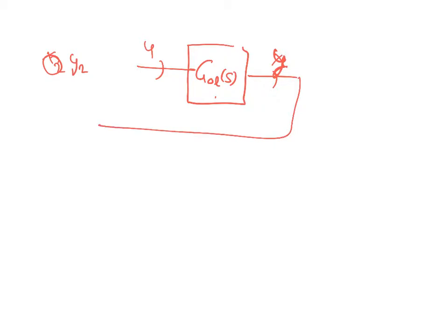So basically you give a feedback, okay? Now you compute your output. This is negative, this is positive, and you multiply it with Kp. So your input is proportional to the error between the reference output and the actual output.